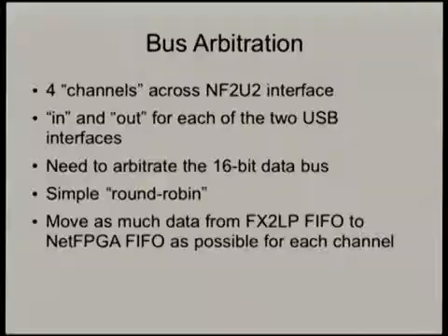So my Verilog code, after it's got the clock right, the next thing it has to do is arbitrate between the 4 data sources, the 2 inputs and 2 outputs that are on those two USB interfaces, and multiplex all that data into this 64-bit data path. And again, it's going to add the 2-byte padding to the front, so that as the packets come in off USB and hit the NetFPGA switch reference framework, they'll all be lined up nicely.